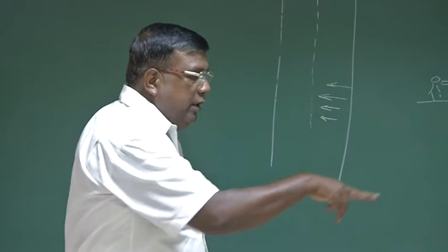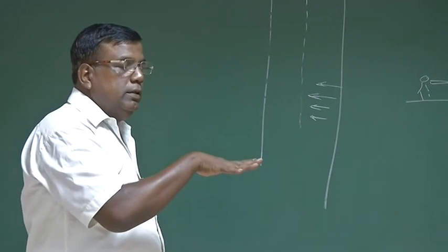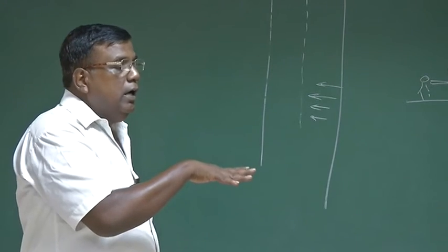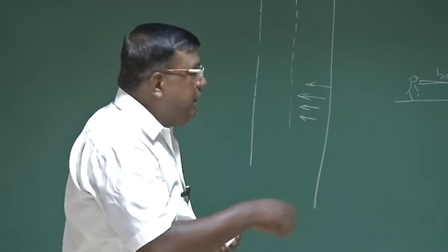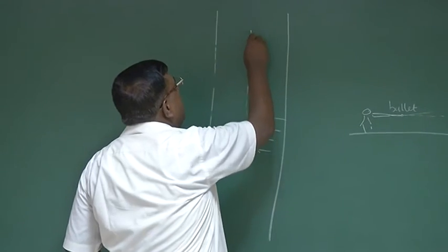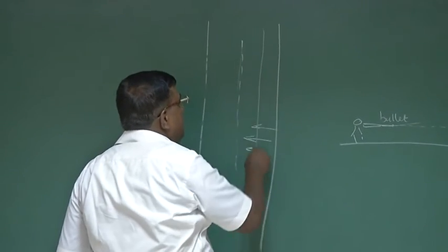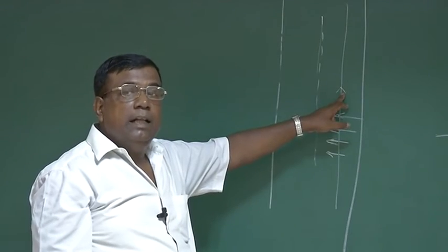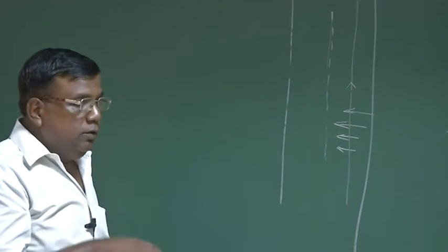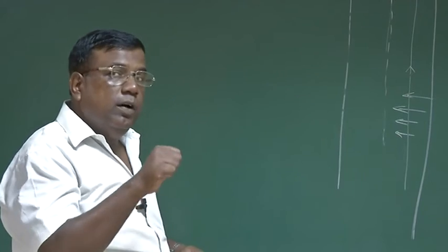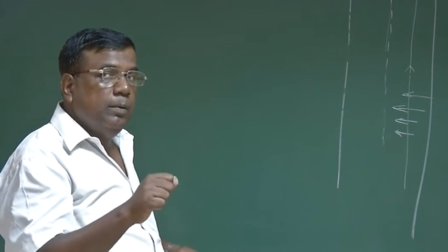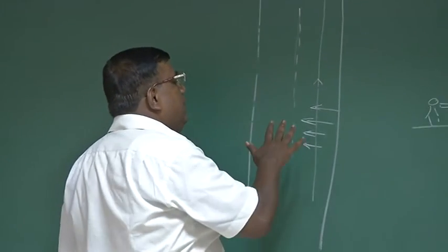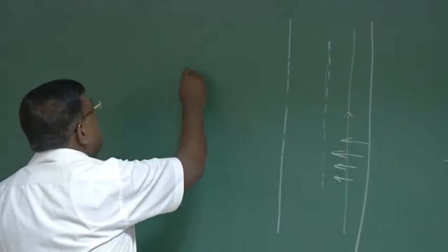I have to land somewhere here. So I was going like this. Now because of wind, I will be drifted like this. So what I will do, I will select a separate line. Maybe I want to actually land here, so I will create an imaginary line here. I will make all my approach aiming at this line. Okay? So what will happen? Because I know that because of the wind coming from the right side, I will be naturally drifted towards the left. So finally, what will happen? I will be flying something like this.